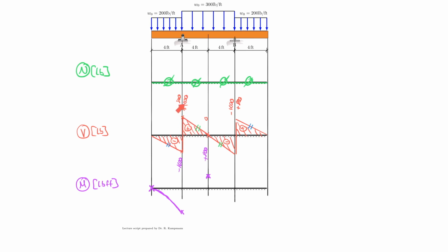So I have a 1200 value here, and then in the middle I have 600, and then here I have 0. So that means that I have to draw a tangent here that is 0. Here I have a very steep tangent, and then I have some tangent in the middle. So that means I definitely end up with a belly up, as my students call it in the classroom. And now I have the left side completed.